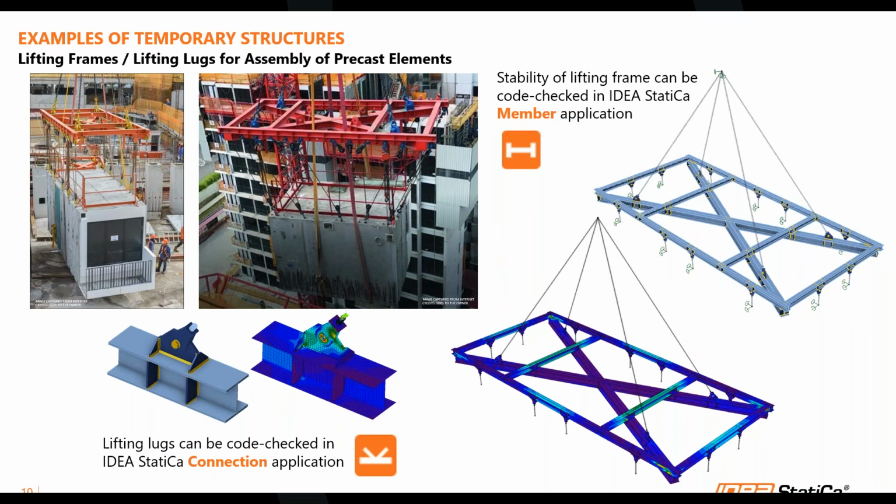For your awareness, IDEA StatiCa can be used not only for connections, but in the Member application you can check the stability of the frame itself, whether it will buckle during lifting. This photo is a good example of how IDEA StatiCa can code check a lifting frame or lifting lugs.